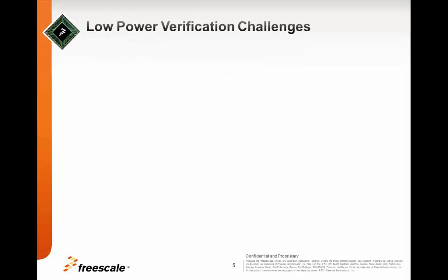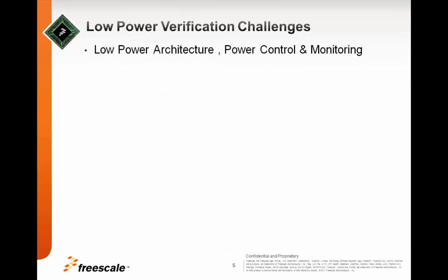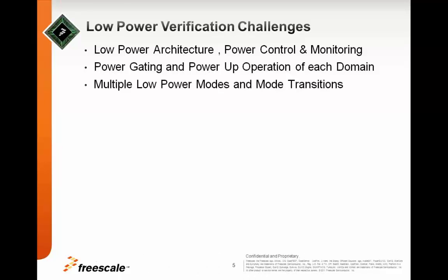Coming to the low power verification challenges, low power SoCs have a complex power management control unit and monitoring unit as well as the extensive power switch fabric logic, which forms the heart of the low power intent in any SoC and thus needs to be thoroughly verified. There are multiple low power modes possible, and the device behavior needs to be thoroughly checked in each low power mode and across the mode transitions, as well as the power gating and the power-up operation of each domain.